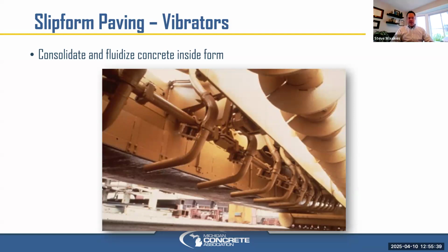So slip-form paving is very similar to putting toothpaste on a toothbrush. The more you squeeze, the faster you have to go along your toothbrush, the harder you squeeze in order to have a consistent line of toothpaste on your toothbrush. If you just stay in one spot and squeeze and then jerk it really quick, there'll be a nice bump in there. So it's matching the speed of the equipment to how hard it's quote unquote squeezing, which it doesn't literally squeeze, but it is being liquefied and then pushed out the back, or the machine is going over top of it essentially. But that's what's going on with slip form paving.